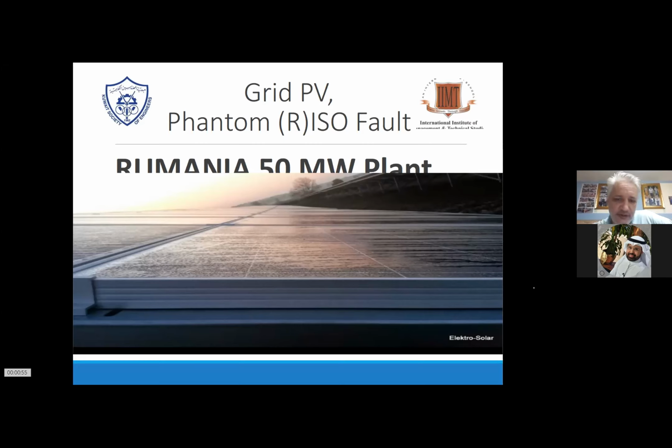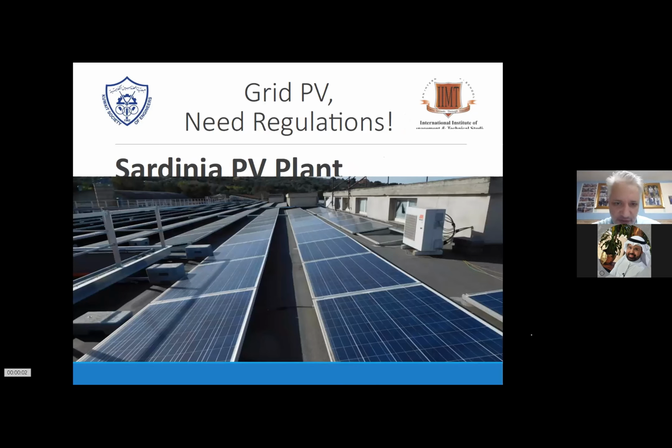So all in all, exceeding 50 square meters of module surface, adding a corrugated roof, which is like a capacitor, and different earth scenarios. So you have the modules, you have the roof, you have the soil, you have the AC inverter, sometimes 100, 200 meters away, and you have the transformer. If they are not interlinked to each other, you will face these troubleshooting problems that the system starts and stops on its own. That's another picture of these systems.